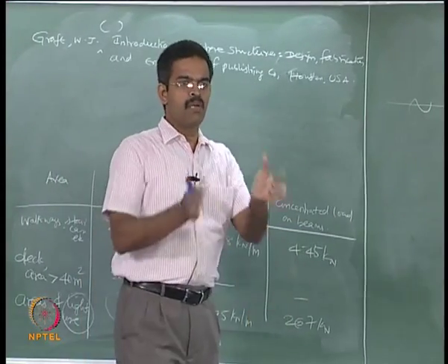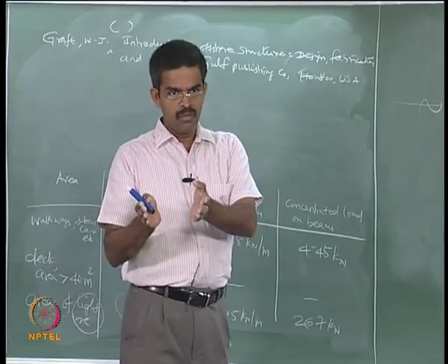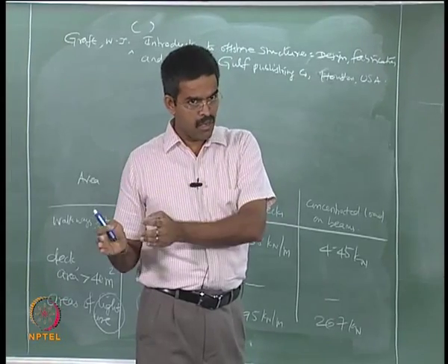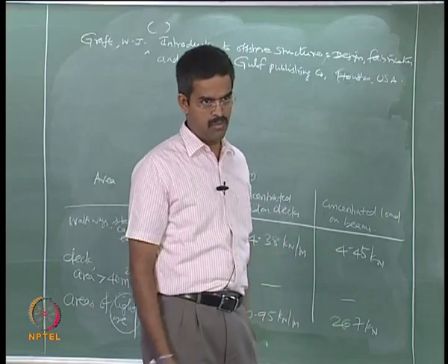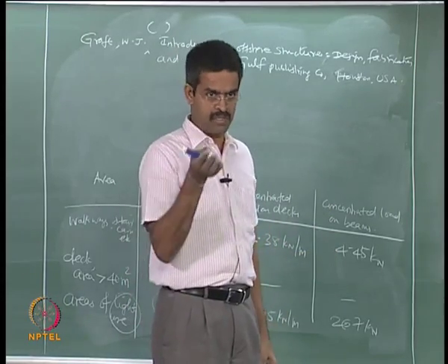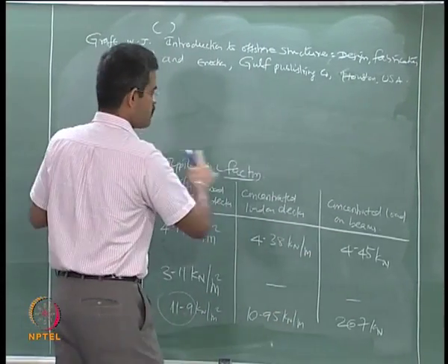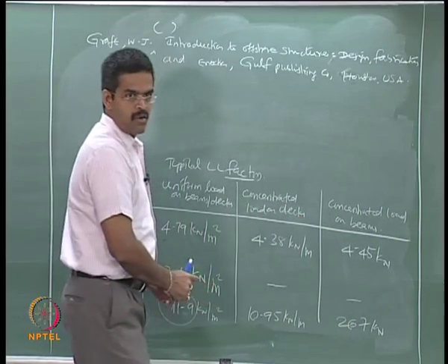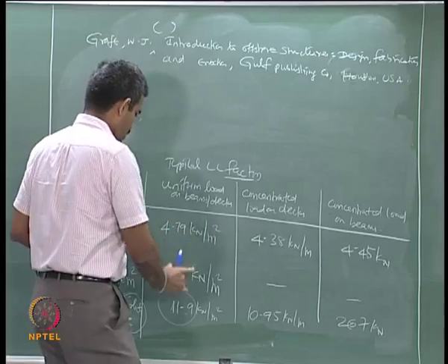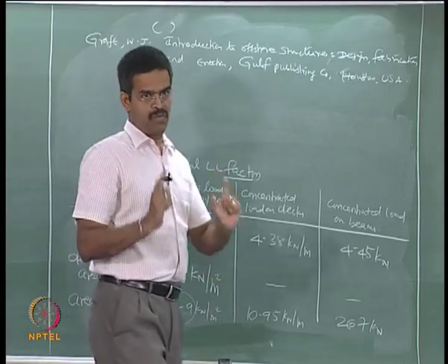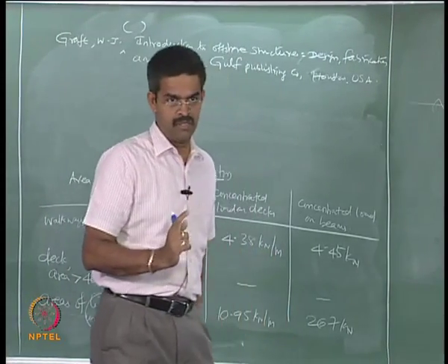Example, building, live load 2.5 kilonewton per square meter, approximately saying 4 persons on 1 square meter area, which is unimaginable load, highly conservative. So, you must appreciate that when live loads were prepared for offshore platforms, there has been very intelligent thought of identifying the magnitude and intensity very carefully. So, there is no conservatism here.